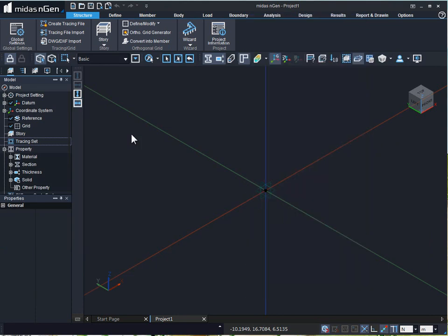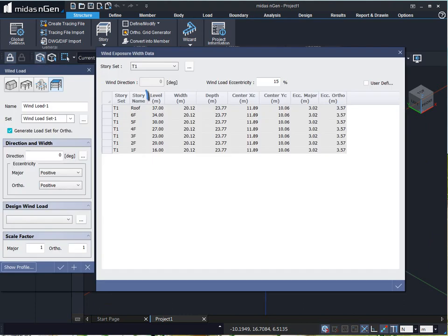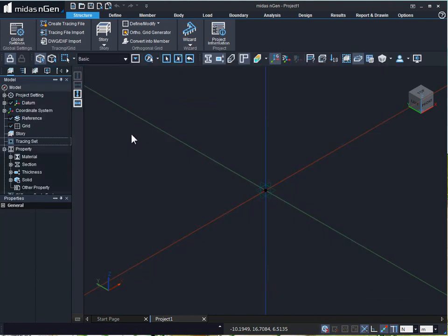While calculating the lateral loads, the story information such as the height of the story, the width of the story, and diaphragm application on the story is required. With the help of height and width of the story, the pressure calculated is applied on the area to get the lateral load wind forces.